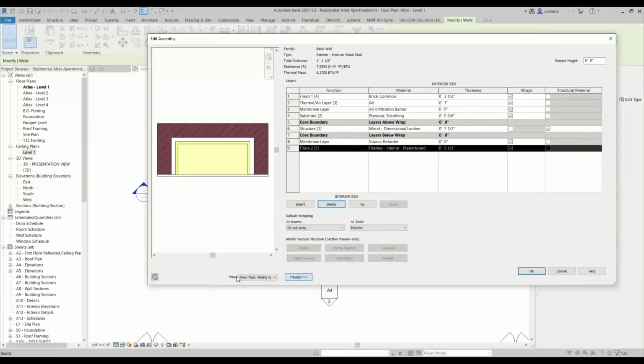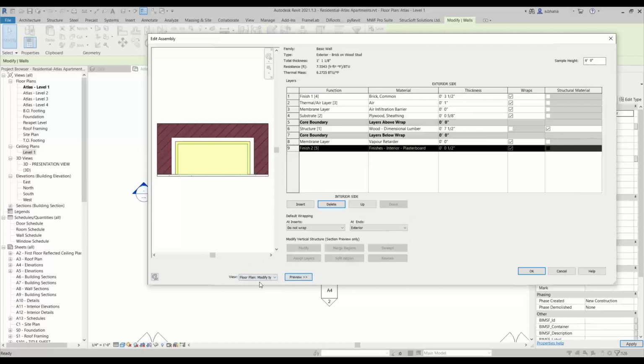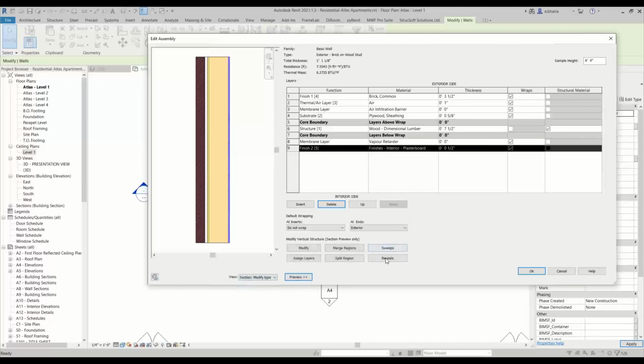Another thing I like to note is if you have any sweeps and reveals in your panels or your walls, just make sure to do a test panel, or create a test MWF panel, so that we can have some reference as to whether the sweeps are going to affect my quick creation if I'm running it on 2,000 walls or 300 walls or something like that.